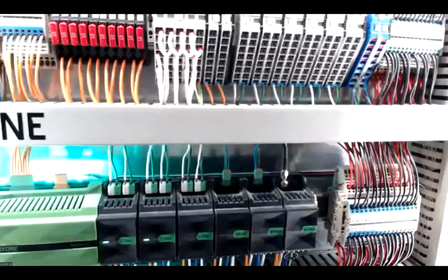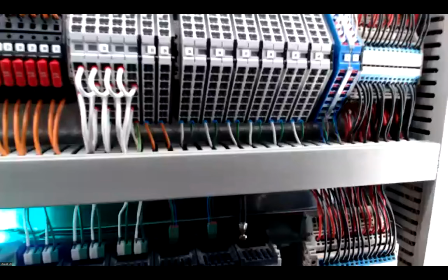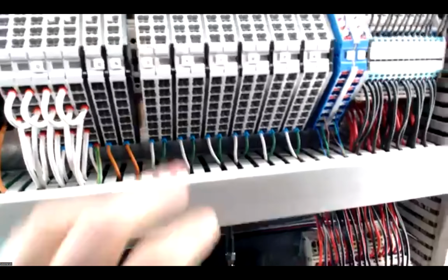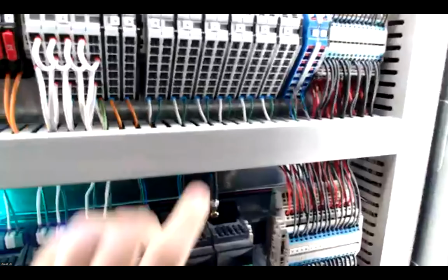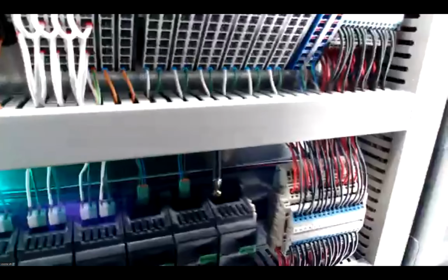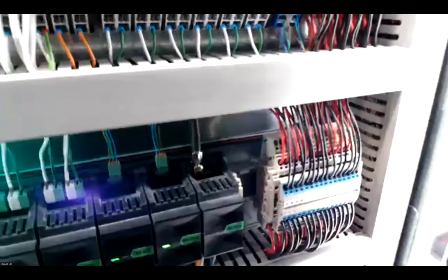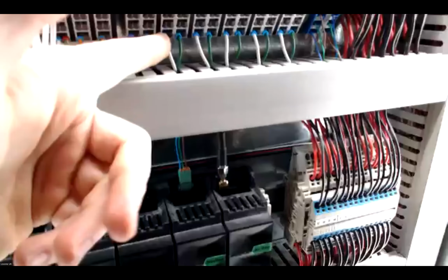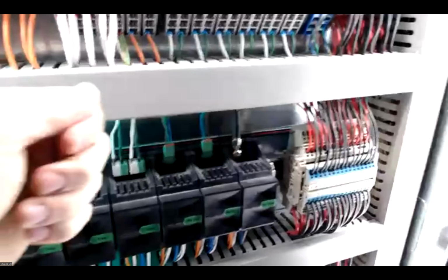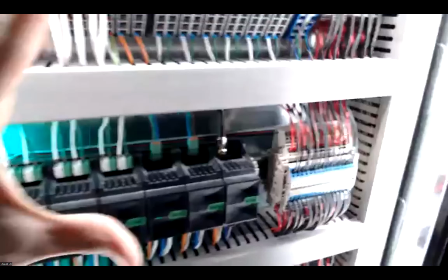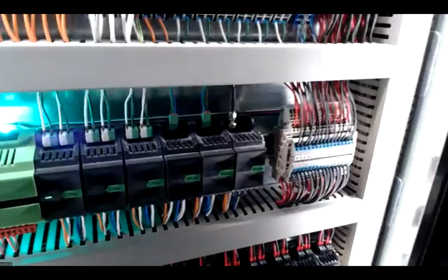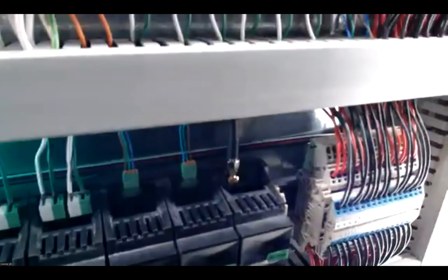Now, what is important to know? These are clamp connectors. So they have a release mechanism, they clamp on the insides. So that is why you do not want to have ferrules on them. Now, in this situation, I do want to say it's obviously done because of consistency. It's not a big deal, but overall, you do want to have just a stranded core, or a solid core to go directly into the clamp connector, because when you go directly into the clamp connector, you have a bigger surface area which you can clamp on, so it creates a better connection. So maybe ferrules are not going to be the best idea in here.